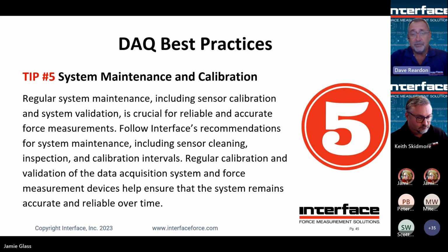Cleaning your sensors is very important. Calibrations, as I mentioned a couple slides ago, you need to follow this stuff to the manufacturer's guidelines to make sure that you're getting the most accurate and reliable data over time.